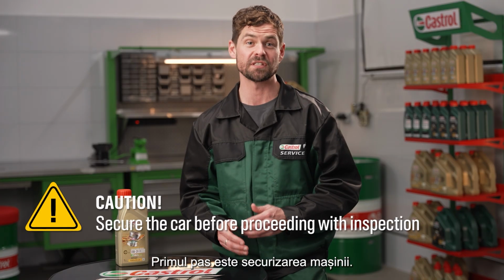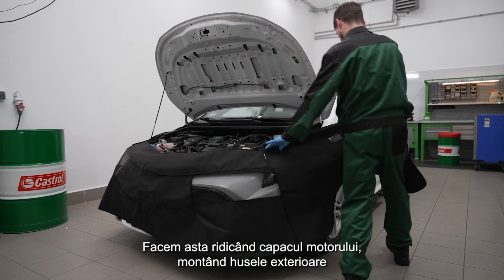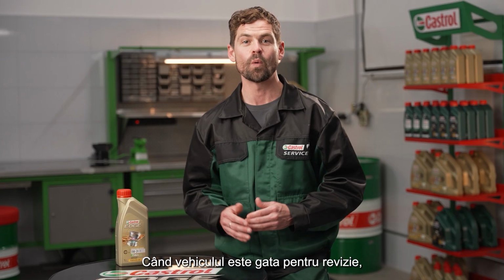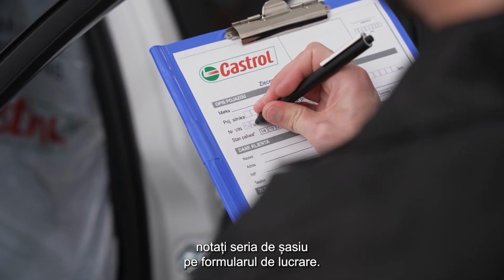The first step is to secure the car. We do this by lifting the engine cover, setting up the outer covers, and placing covers on the driver's seat, steering wheel, shift lever, and floor mat. When the vehicle is set for inspection, write down the VIN number on your work order form.